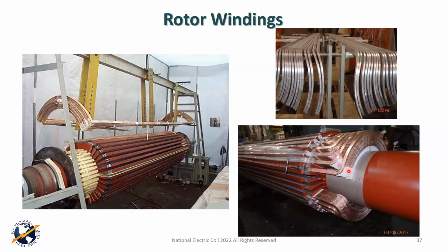And then we have the turn-to-turn insulation. There'll be a creepage block and some insulation on the top, which is the ground plane in the slot that's underneath the wedge. And then later we're going to talk about the retaining ring, and you'll talk about retaining ring liner insulation that prevents the coils on the end winding here from going to ground to the retaining ring.